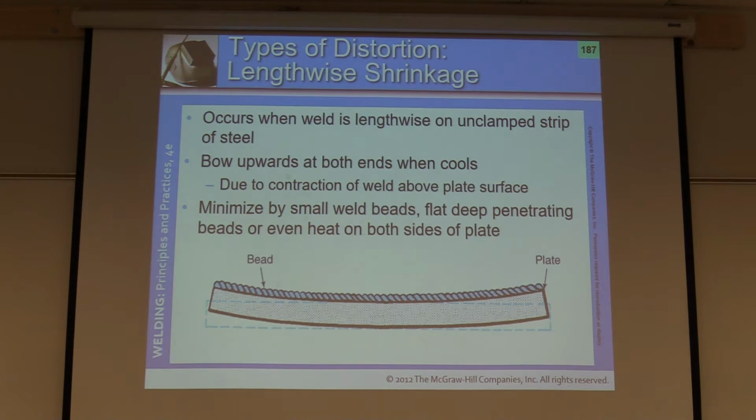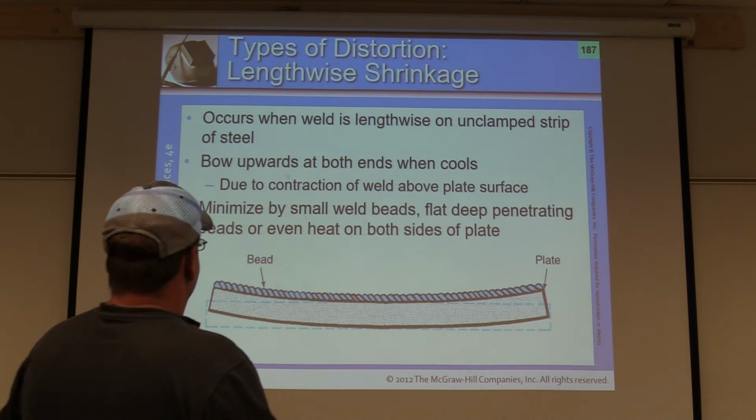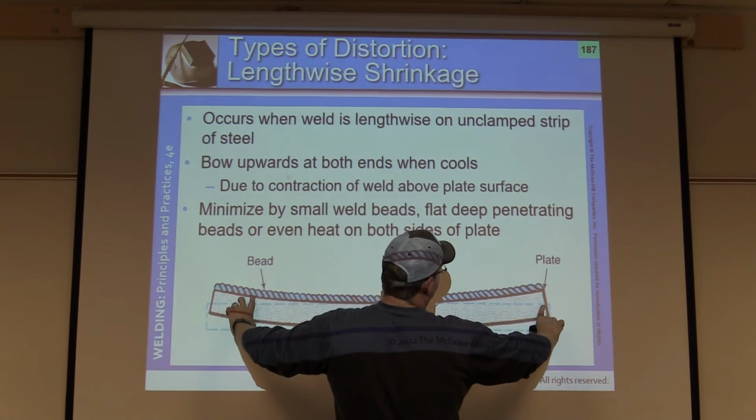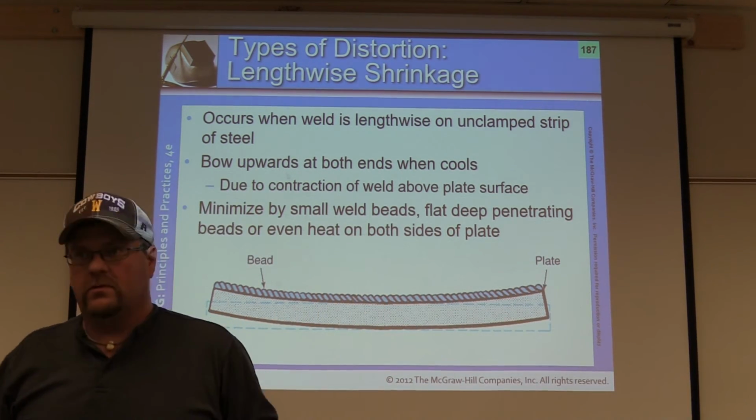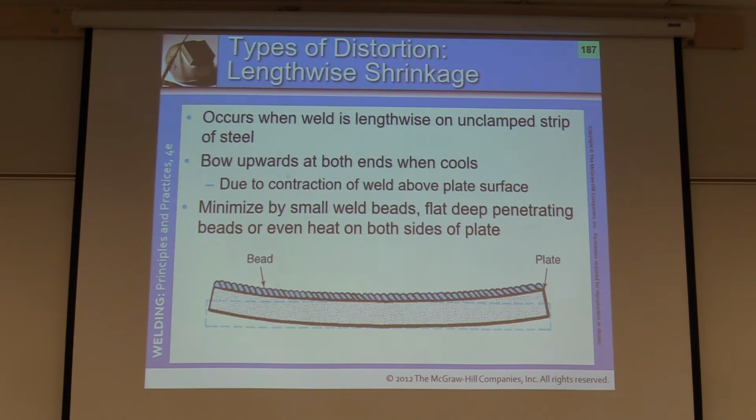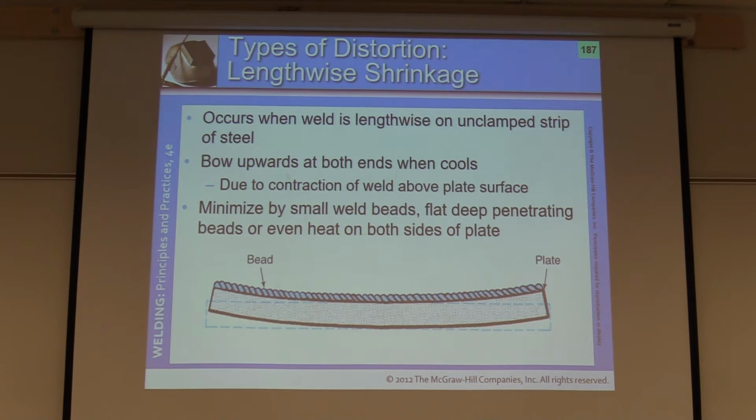So before welding it was nice and flat. After it was welded, the weld contracted. It created stress and shrinkage within there, also resulting in distortion. Stress, on the other hand, is a force that will cause distortion later unless it is relieved.